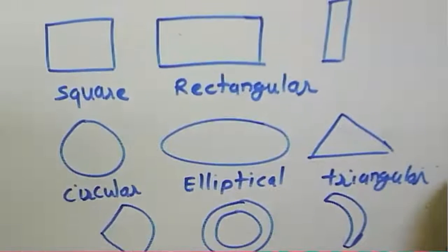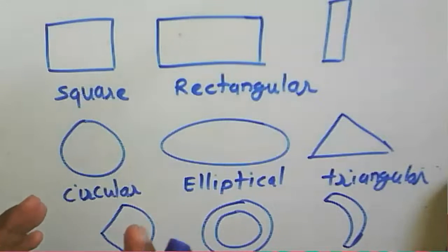Now these are the various types of patches. Mostly, the preferred patch is the square shape, because whenever you are designing an antenna array, identical elements are used to develop the array pattern. In terms of polarization, if we use a rectangular, square, dipole, or triangular patch, we get a linearly polarized output. But with the other elements, we get circular polarization. So for what purpose the antenna is to be used, what our aim is, whether linear polarized applications or circular polarization, according to that we need to use the various configurations of this microstrip patch antenna.